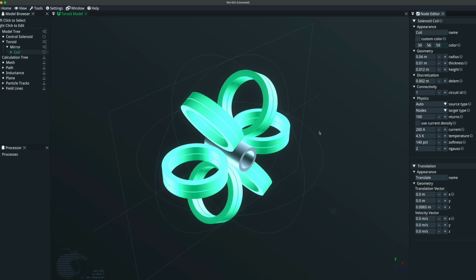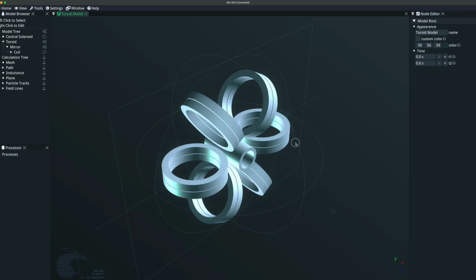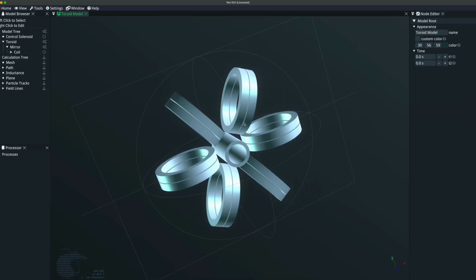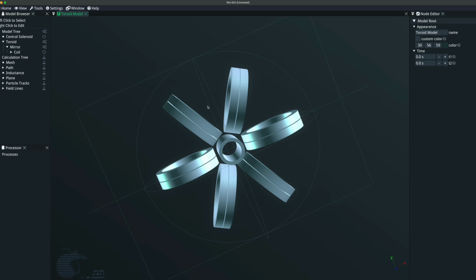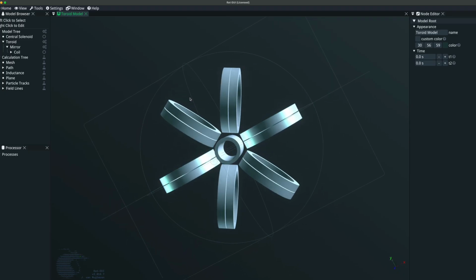So now, why is this important? Basically, in Rat, the calculations are based on direct Biot-Savart, so that's an integration method. And this way, there doesn't need to be any meshing of the air, and it's sped up with the multi-level fast multipole method. The MLFMM is already explained in the previous tutorial in this series, so I will put this in a